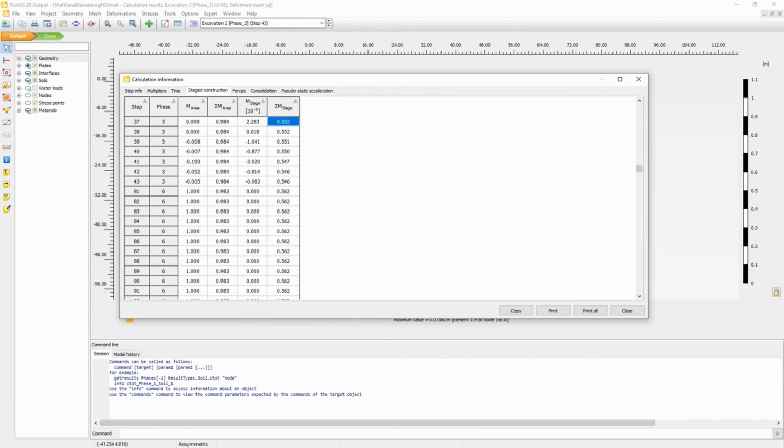This is what it does. And it does this control by an arc, I would say. If you look at the force displacement diagram, it's controlled by an arc. For this case, when you start to have a loss of stiffness that generates large displacement, Plaxis starts activating and tries to reduce the load increment that we are considering. So this is solely due to the arc length.